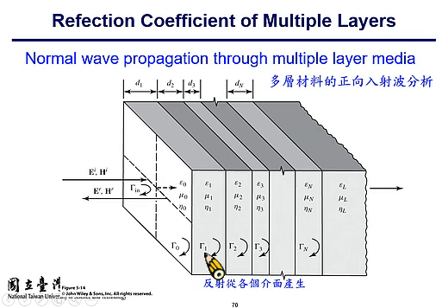A very broadband matching. So the method is to adopt a multi-layer structure, a higher order design. For this multi-layer structure, the difference between the permittivity in adjacent layers is very small. As long as you can add many more layers with small differences, then the reflection between each layer can be minimized.